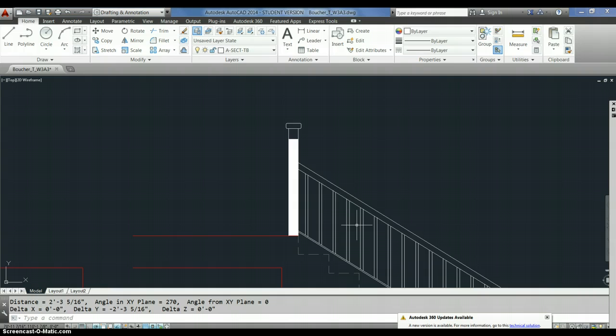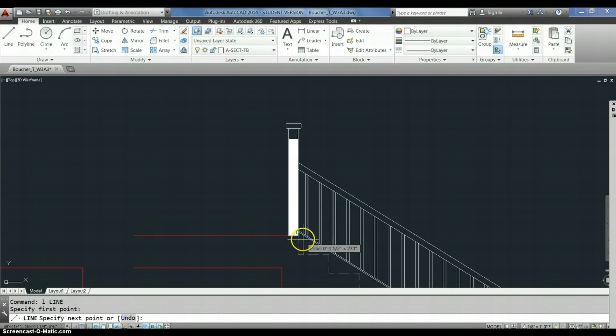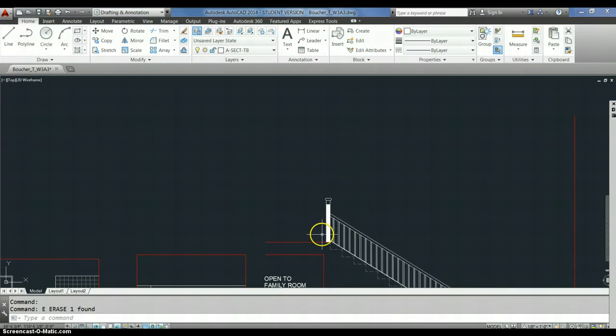Okay, here is the weird thing about stair rails. If you do them parallel to this line right here between these two treads, which is, I know how we drew it. Okay, that's totally how you draw it. Sometimes they don't line up quite right. The code is that it has to be between 34 inches and 38 inches at every point along the way. And so what we usually do is we'll pick an average of that. I'll start at 36 inches at the top, at the bottom, 36 inches at the top, run a line between the two. Okay, so in other words,